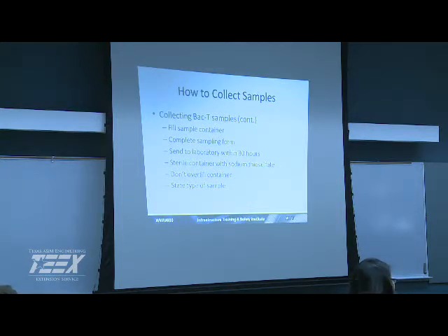Who's pulling samples after? I know we had a conversation yesterday about distribution, but depending on how you're doing your repair, it depends on what you have to do, if you have to do a slug method or if you have to swab it. It really depends on what you have, whether or not you have some kind of introduced contamination, like a failing septic system leaking into the trench. Yeah, like that, or the pipe gets contaminated during installation, things like that. Things to look at.